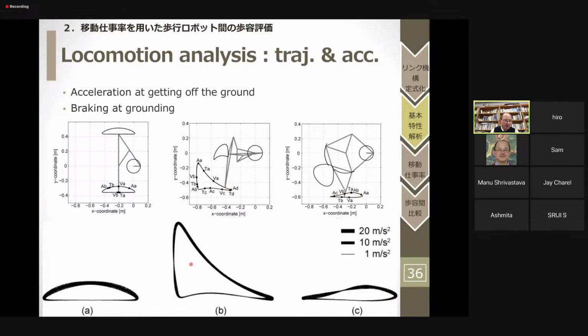The bottom picture represents the speed and the acceleration of motion, how the force or the acceleration is generated. It's clearly described, speeding up, slowing, or speeding up, falling down. And then the Theo Jansen mechanism is naturally lifting up, then gradually touches the ground very smoothly.